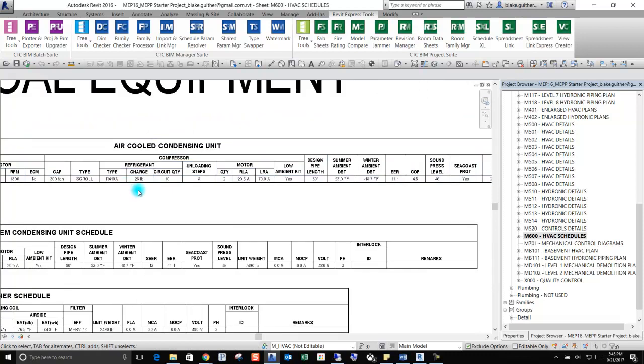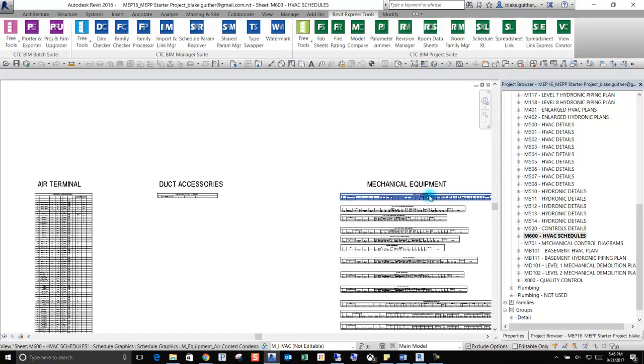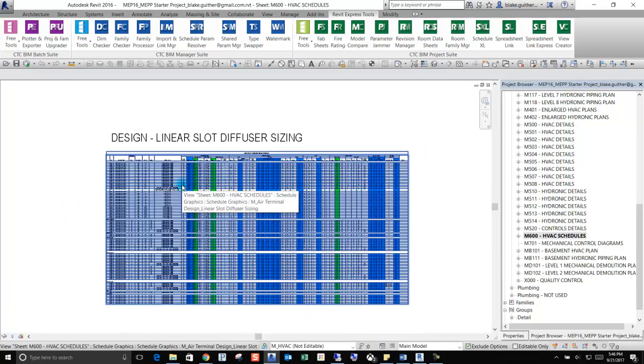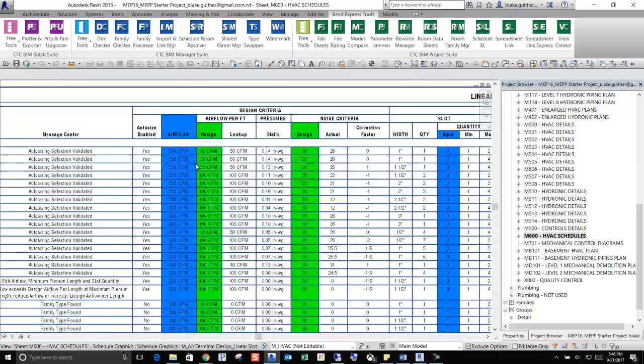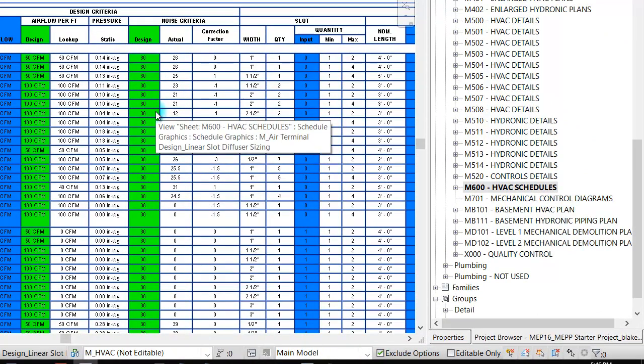But schedules alone aren't enough. We have a lot of auto-sizing families. We have host family functionality, and we have families that can move their connectors anywhere the user wants them. That also requires, like I said, those sets of parameters for each connector. But things also need to be thought through in regard to auto-sizing. This is a sizing schedule, which we'll talk about more, but essentially this outlines how these parameters are going to be used in this next evolution of auto-sizing and automating our industry. There are calculated values, final values, overrides, and inputs.